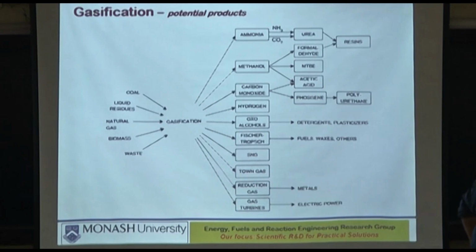So when you gasify coal, what happens is, and I was going to go into the fourth slide and we'll be discussing that there, the coal gets dried. So what remains is moisture free coal. Then it gets devolatilized or pyrolyzed. That releases some amount of CO, CO2, methane and hydrogen. What remains is carbon or char as we call it.